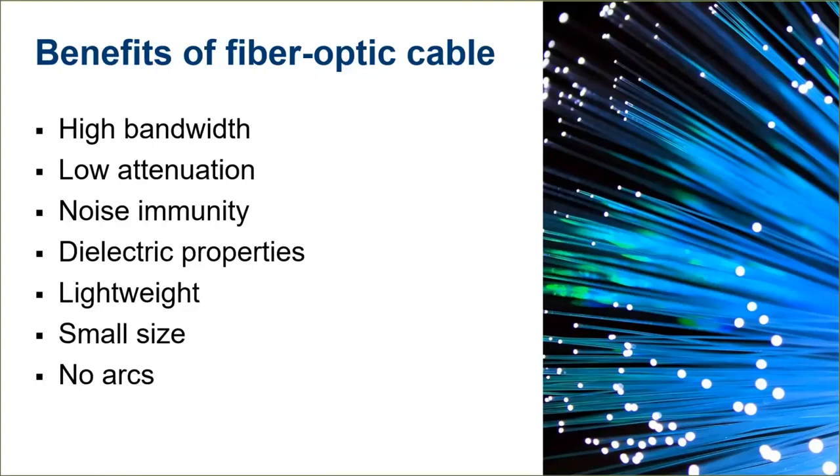The additional weight and cost are not very large, but additional fiber provides an invaluable resource even if it's not needed at the time of installation. And of course, the transmitted light does not cause any sparks, electrical arcing, or arc flash, even if the cables are broken or damaged. This allows fiber to be used in applications where flammable gases and other safety factors are concerned.